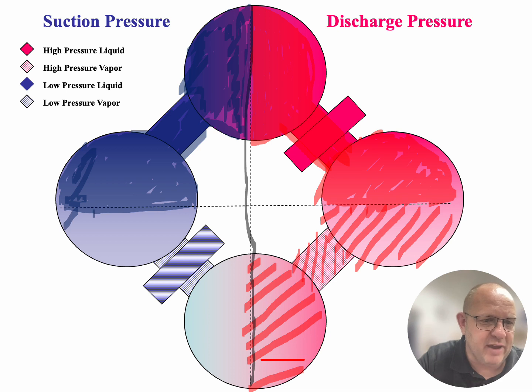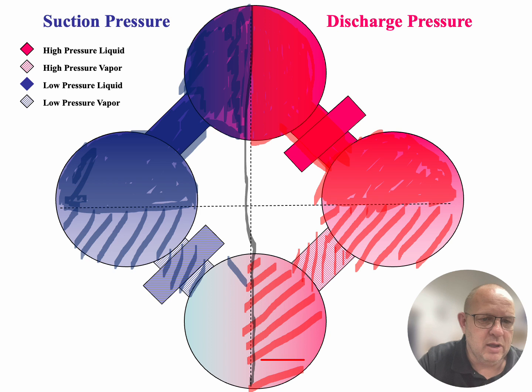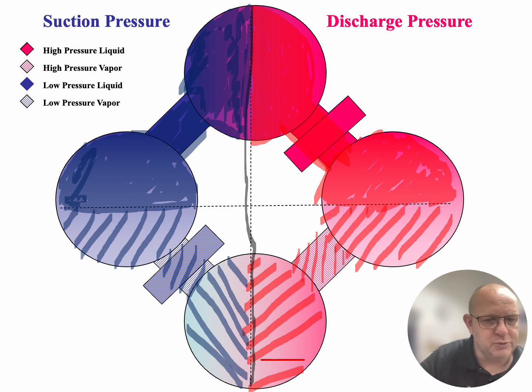So on this side of the evaporator, we're going to put these dashed lines, and that's going to illustrate for us that on this side of the evaporator, that has taken that liquid refrigerant that came to it from the expansion device, and it has turned it into a vapor. And that's perfect for us because we have a vapor only pump at the compressor, and if we were to send any liquid into our compressor, we would end up destroying that compressor itself. So there you go. That's the states of the refrigerant as it's passing through the different components of the system.